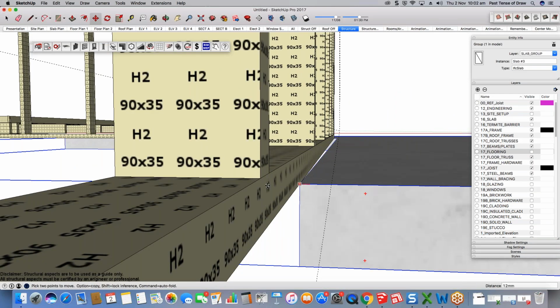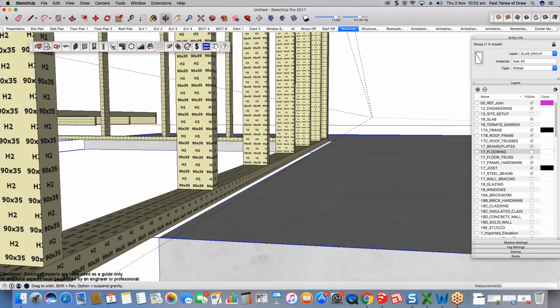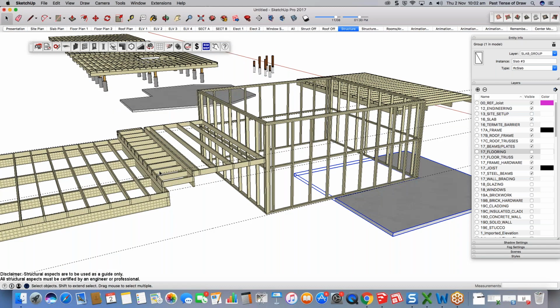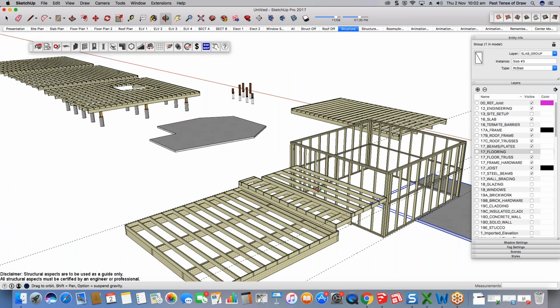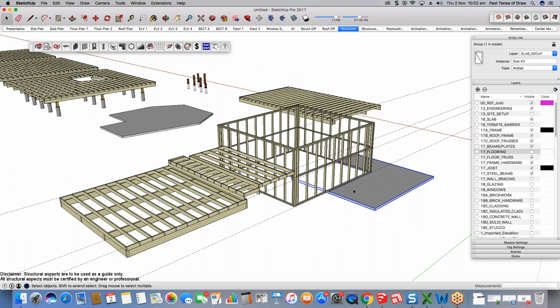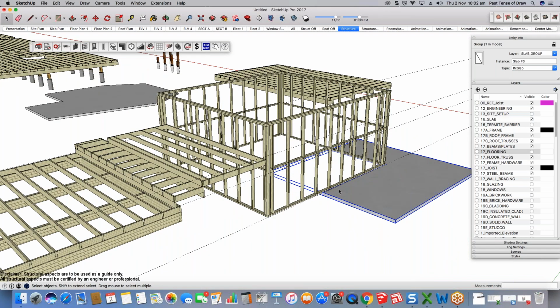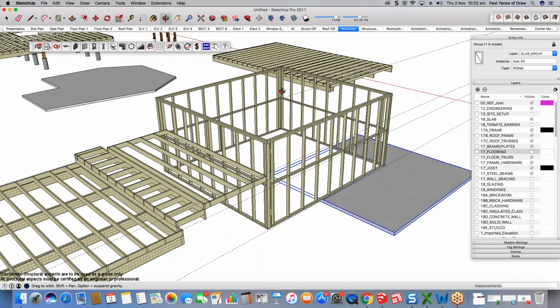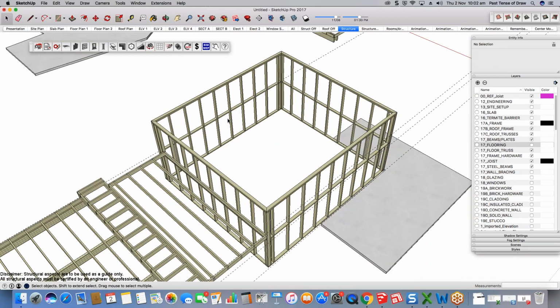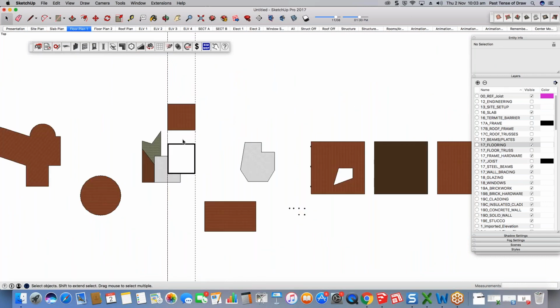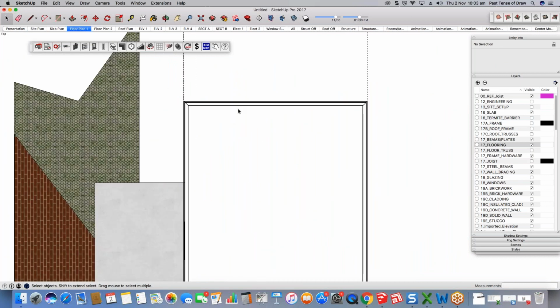If that is the case, the best way to do that is to go into your structure scene so that you're not getting confused and accidentally grabbing points that don't relate to the finish items. Getting into the structure scene is really important. In fact, when I'm modeling, even with my internal walls, I typically model in the structure scene. Sometimes I'll model in the ground floor plan too. The ground floor plan will turn off your finish layer by default, so your internal lining.